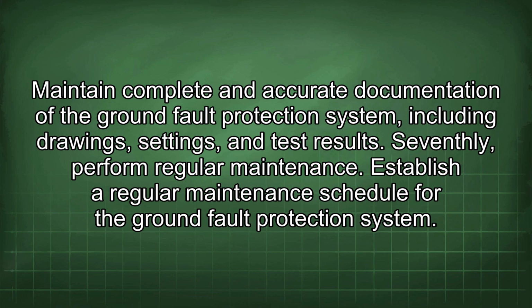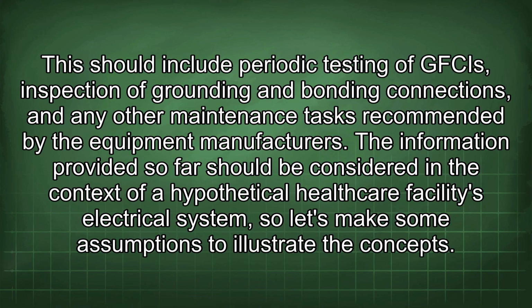Sixthly, document everything. Maintain complete and accurate documentation of the ground fault protection system, including drawings, settings, and test results. Seventhly, perform regular maintenance. Establish a regular maintenance schedule for the ground fault protection system. This should include periodic testing of GFCIs, inspection of grounding and bonding connections, and any other maintenance tasks recommended by